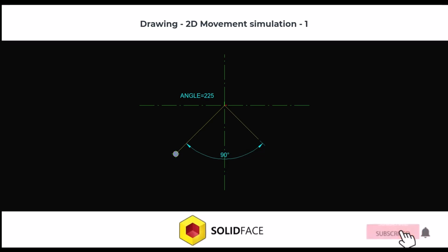This video shows how to simulate the movement of a pendulum. Initially, a horizontal line of a specific length is created with a rotation angle variable. A rotation command based on this angle is activated, simulating the pendulum's movement within a specific range of degrees. To enhance the simulation, adjustments like loop movement and automatic reverse motion are shown.